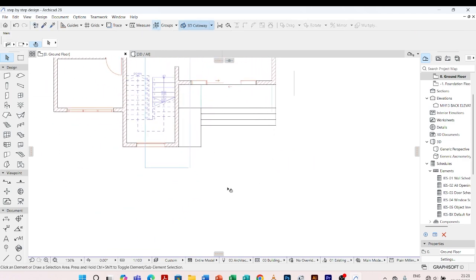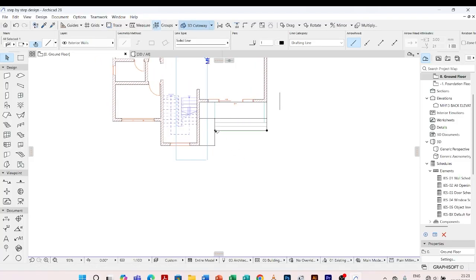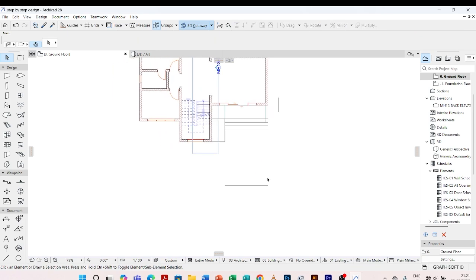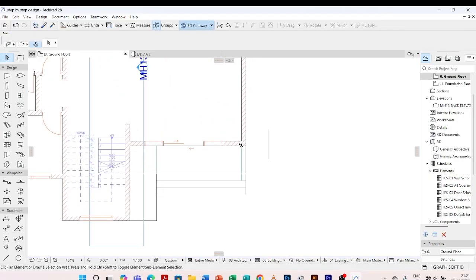Then the same way, I'm assuming my cars are parking here from this step, so I'll need a distance. Let me give it a distance of 5.5 meters in front. So I'll Control Shift D, that is for moving a copy. I'll give it 5.5. Actually, even 5 meters. Can go with 5 meters. Enter. So that means I will want my parking to stop here.